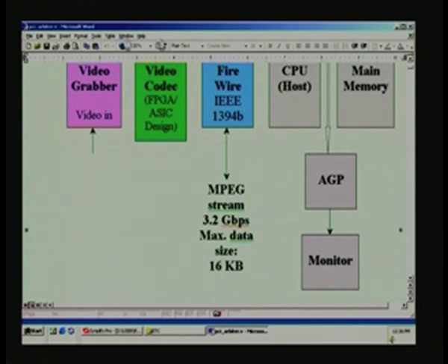Just with 2 channels we can use it for communicating between 2, and if you have multiple such computers, you can network them, in which case this same FireWire, the very same hardware, will cater to 63 basic serial interfaces, and if you want you can expand right up to 64 kilo, I mean, it's not bytes, 65,536 such nodes you can connect here.